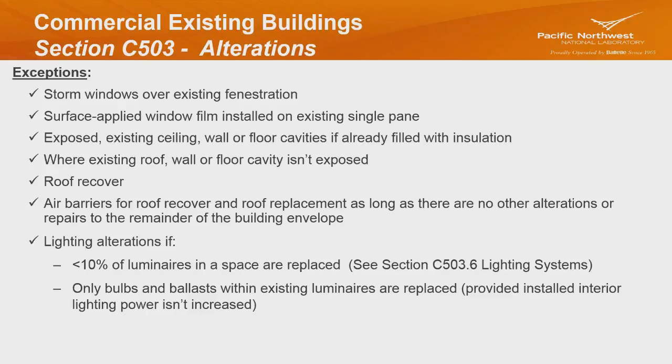Roof recover, there's an air barrier exception for the roof replacement. Now let's get to lighting. Lighting alterations: if it's less than 10% of the space, you're exempt. All right, there's some ambiguity in the code here.